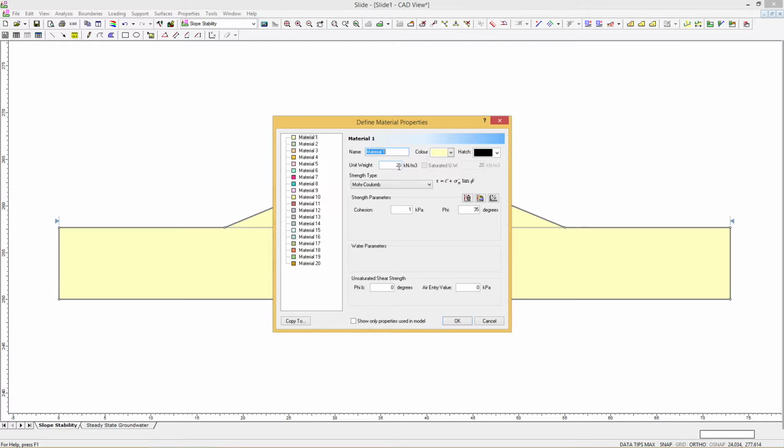The water retention curve shows you the relationship between permeability or hydraulic conductivity and matrix suction. But that is a little bit more complicated to understand at this level. For your technical engineering, don't worry about this part. Just simplify your life. Use unit weight, the last one, and the weights you are given, use them as unit weight and as total unit weight. And for the analysis, let's use finite element analysis.